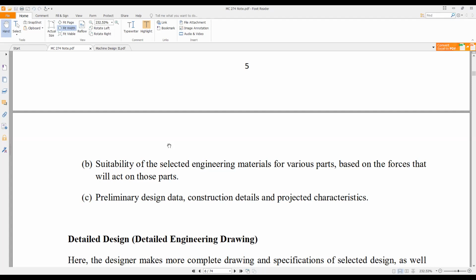If it's going to be used in an area where there will be repetitive cyclic loading, like there will be fatigue loading of the member, and you choose a member that is very brittle, you see that it will fail within a short time. It will just break apart.